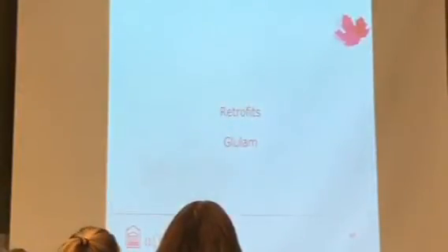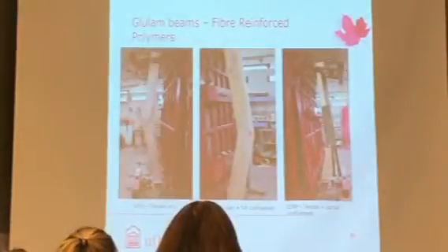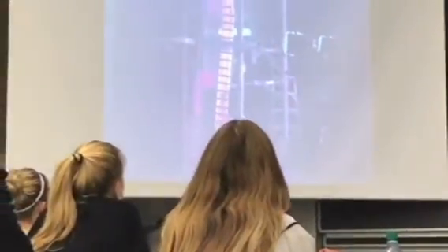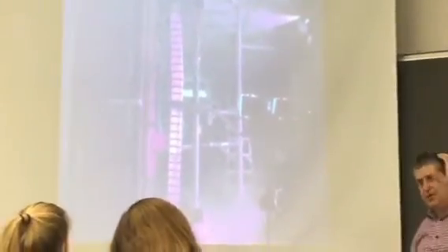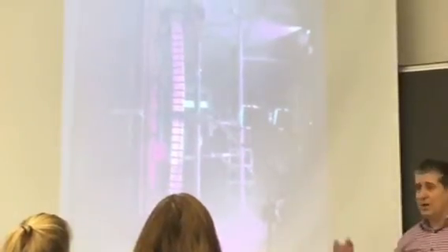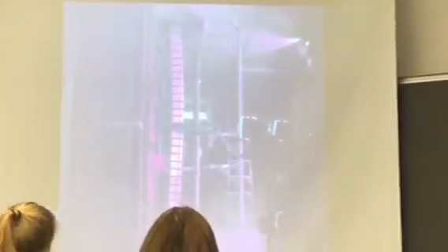We did FRP retrofits of beams, and also retrofits of CLT, where, again, I'm really cheap when it comes to these things. You go in the lab and you see that every time they remove a pallet, they take those straps and they throw them away. And I said, why can't we wrap those straps around the transverse layers? They always rotate and they give us this rolling shear effect. So if we just strapped around it, we can actually enhance the capacity. So we did this, and you can see the result of that.